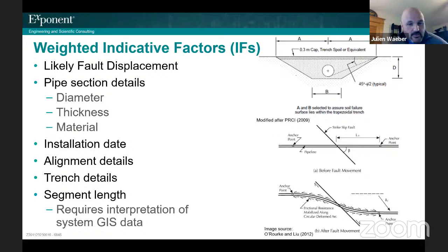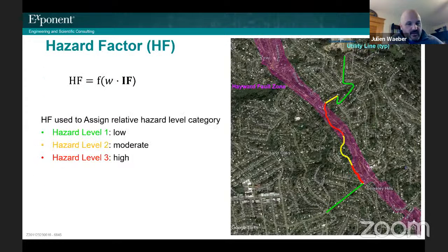And what is the incidence angle of crossing, for example, because that is going to dictate whether this pipe would fail in compression or tension. So you can do this ad nauseum with many different parts of your system. The point is that you can do a semi-quantitative assessment of your system based off of each of these components, and then bring that back to what is, I think, an elegantly qualitative assessment of your system.